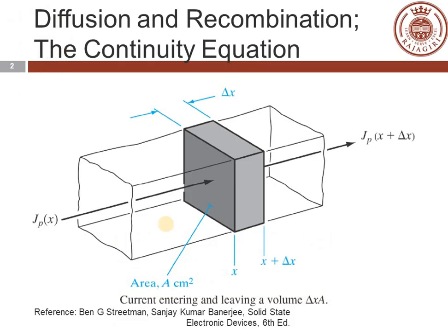Effects of recombination on diffusion of excess carriers have been neglected till now. If you consider the previous sessions, we haven't considered the recombination part. So in this part we will be considering the recombination of excess carriers. Here the effects of recombination should be considered, as recombination can cause a variation in the carrier distribution. As an example, you can see this diagram here.